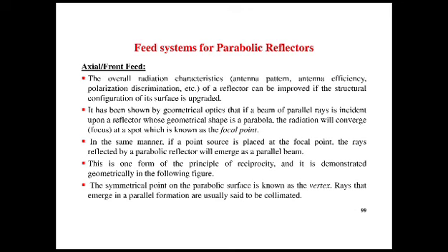Feed for parabolic reflector: axial front end. The overall radiation characteristics of the reflector can be improved and the structural configuration upgraded. If it is shown by geometric optics that a beam of parallel rays is incident upon a reflector whose geometric shape is a parabola, the radiation will converge at the spot which is called the focal point. In the same manner, if a point source is placed at the focal point, the rays reflected from the parabola will emerge as a parallel beam. This is one of the principles of reciprocity and is shown in the figure.